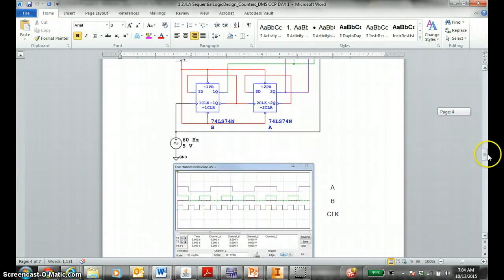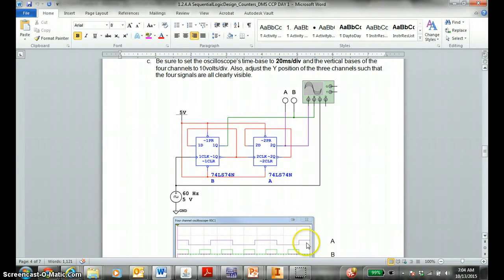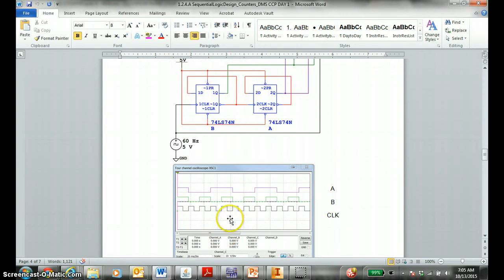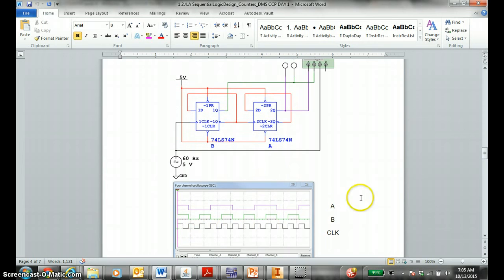This is the 2-bit counter you made with the oscilloscope attached to see the clock signal, the upward positive edge trigger, and then it stays on the high signal for so much, and then has a falling edge signal back to 0.